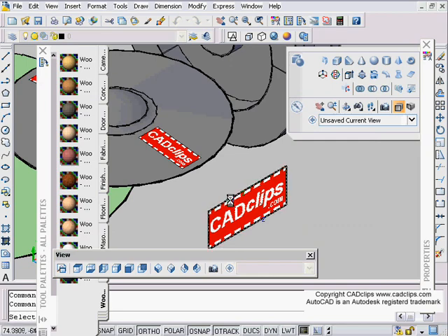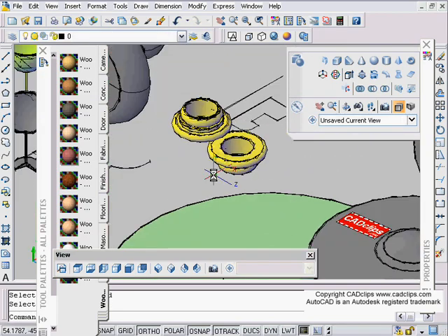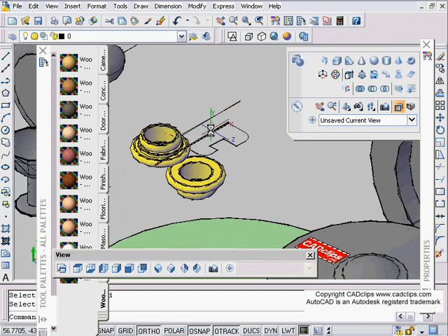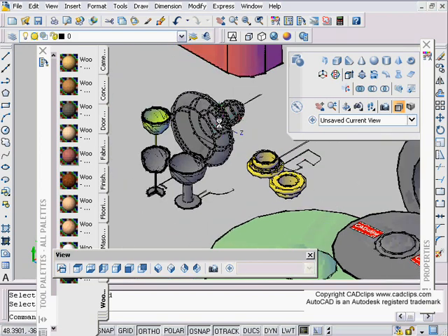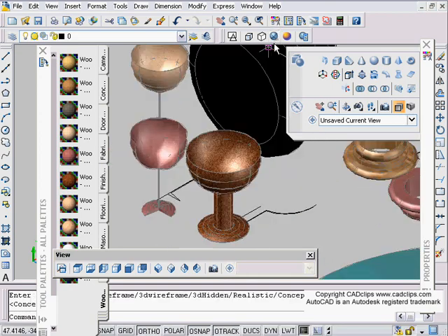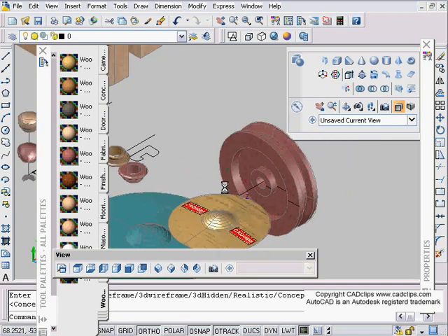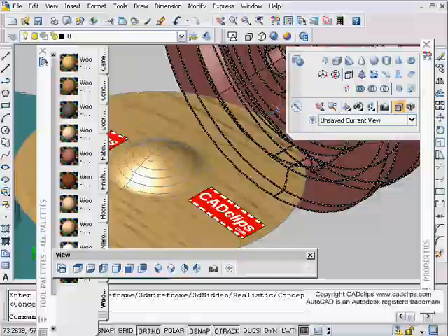Kind of fun. So lots of different stuff you can do with the revolve command. Okay, some different examples here. Depends on the axis. The main thing is your axis has to be on the same plane and the object has to be able to revolve around it, and then it can't interfere with itself as it revolves around, and then from there it's a matter of adding in your materials and some stuff that we're going to talk about in some future lessons.